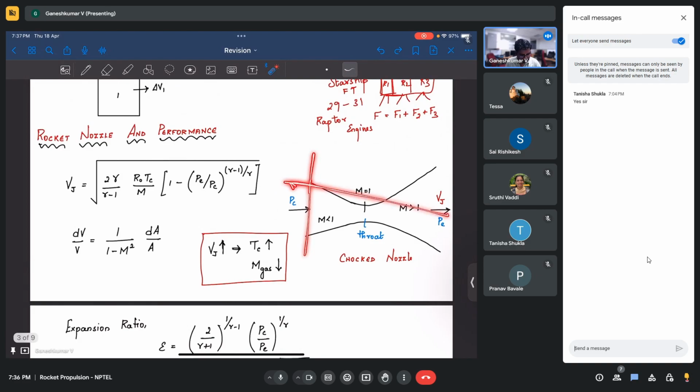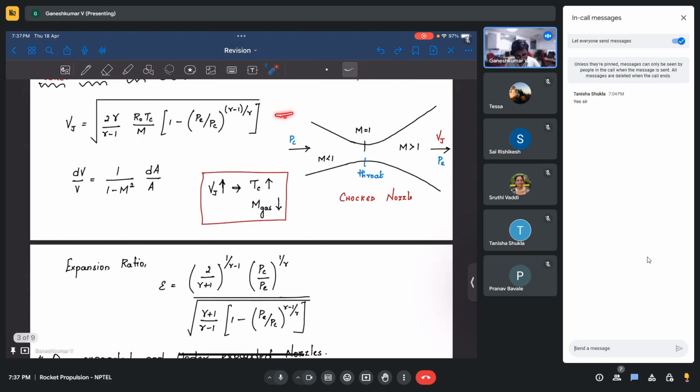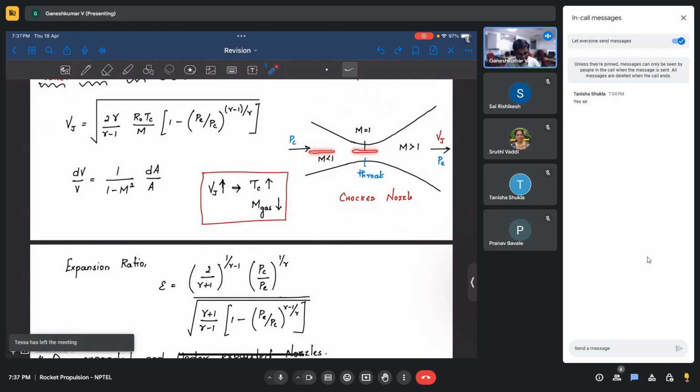There is a pressure gradient which drives the flow, so flow is going to go through the nozzle. Now, while it is going through the nozzle, the temperature here is high, which is a thermal energy. While it is going through the nozzle, it is going through a constriction. The areas keep on reducing, which means as per mass conservation, what should happen?